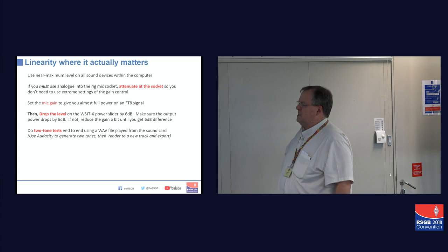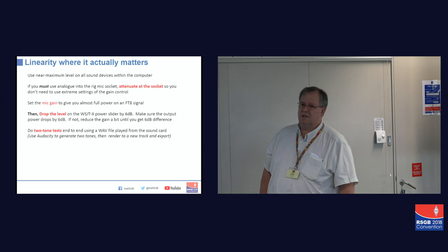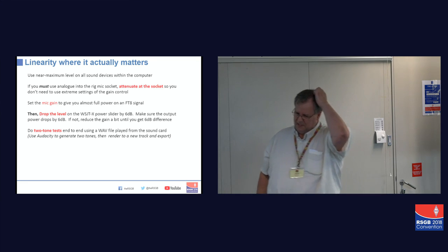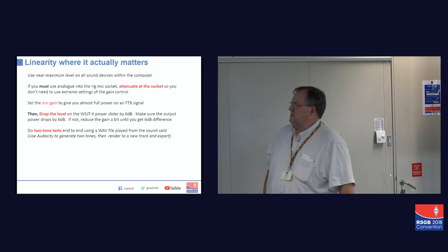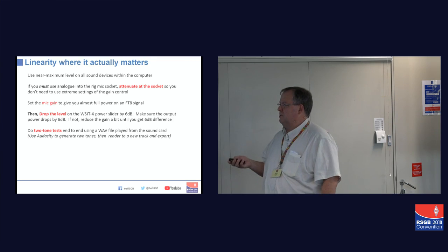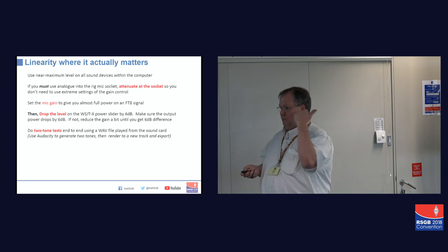Now, the best way of testing it is the same as it is with sideband. Do a 2-tone test. Oh, that sounds hard. You used to have all these complicated oscillators and very fancy kit. Well, these days, I just generated 2 nice pure tones in Audacity, made a new track and exported it. The instructions will be on the website, so it